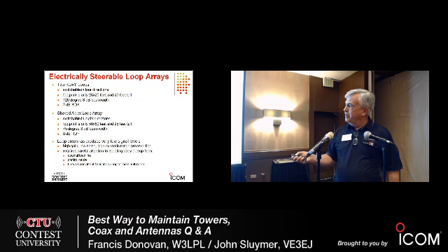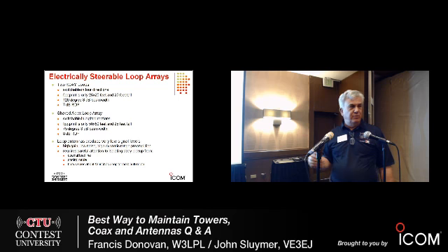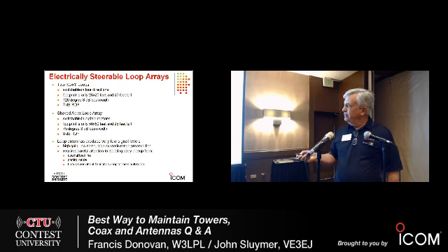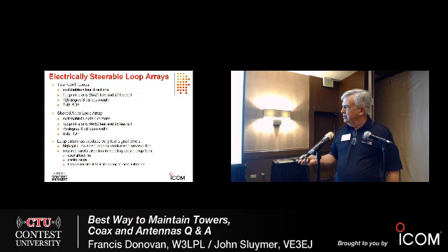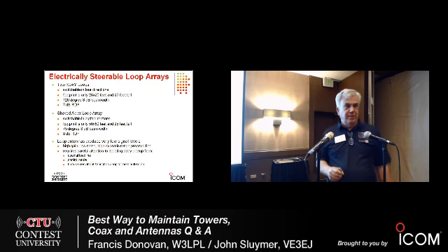A little bit better performance is this newer shared apex loop array that will be described in the antenna forum tomorrow. The biggest difference is that its beam width is a little bit reduced. It's about 75 degrees wide across the main forward lobe of the antenna. And this is also a pretty small antenna, about 50 by 50 feet, and it's also 25 feet tall. And a general comment again about loop antennas is all of them without exception produce low signal levels, so you need a preamplifier and you need to pay attention to decoupling signals arriving from outside of the loop.